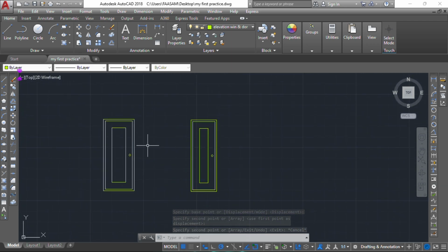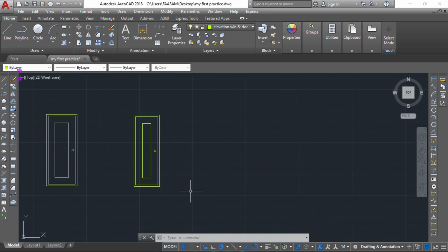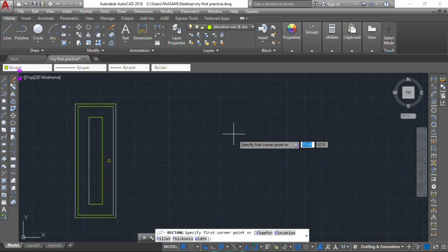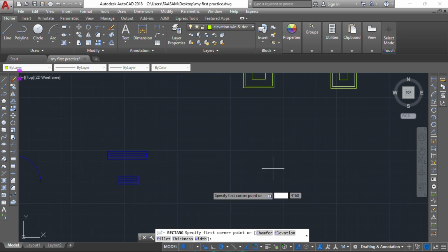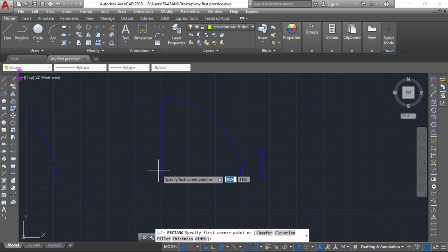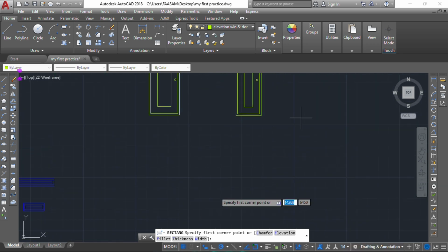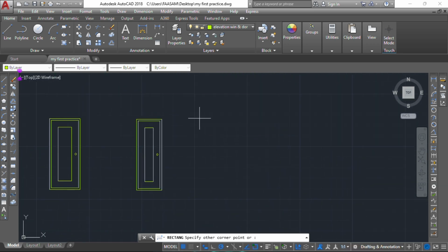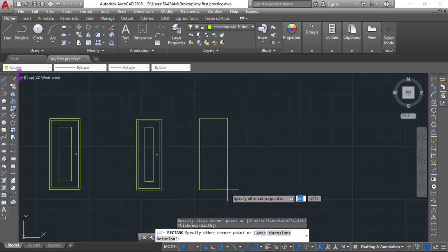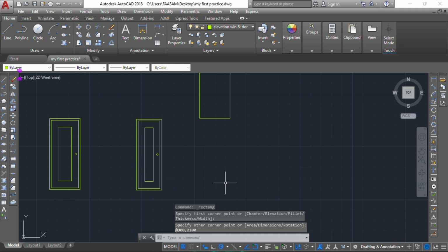So now let's go ahead and create our external door, which is our entrance door. And then we definitely will be having, just like what we are having here, a larger door of 900 and a smaller door of 300. So let's do that. A bigger door of 900, which is this. So let's say 900, 21, right?